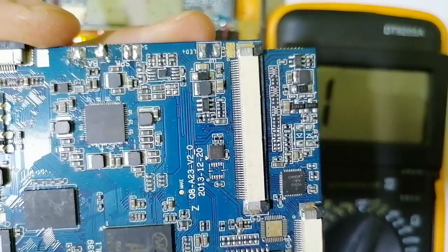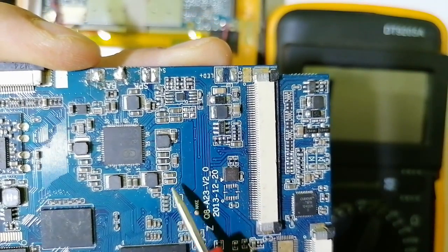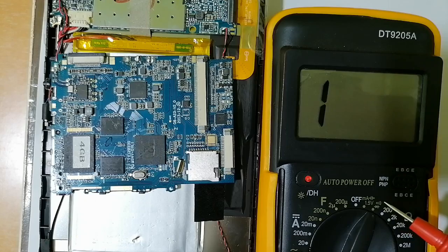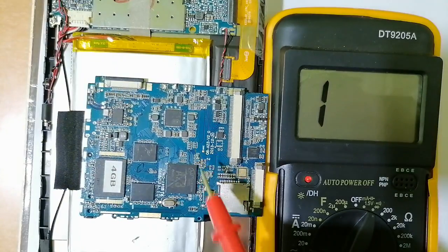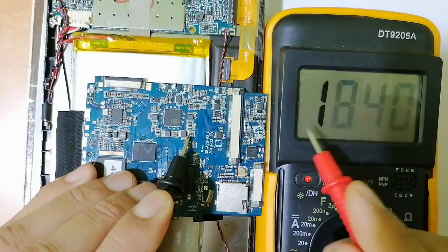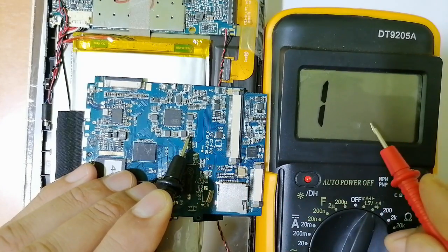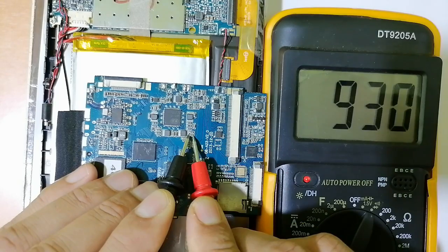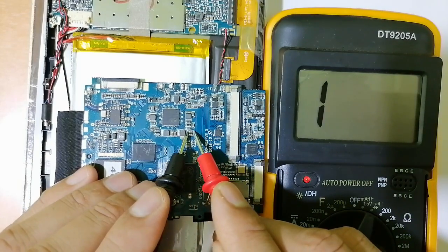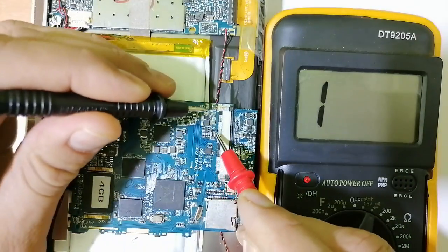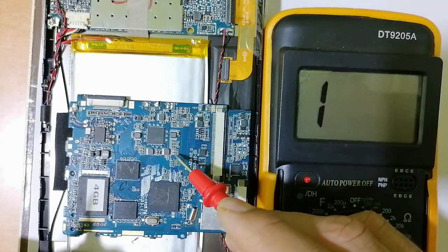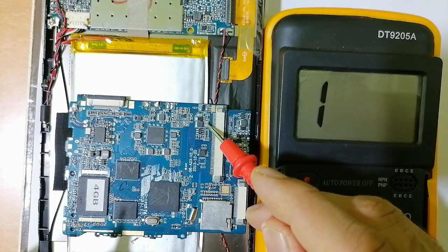You should replace it. Let's now check the ceramic capacitors. As you can see, we always select the continuity option. A bad capacitor is a capacitor with a low reading. So let's check, for example, these capacitors. This is good. You should get a reading over here, a reading of more than 100, as you can see. 900. Let's check this one also. Also the same reading. Let's check this one over here, as you can see. So this is also a good capacitor.